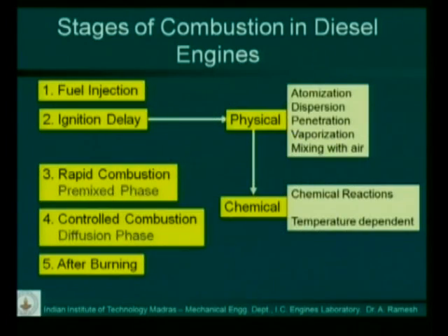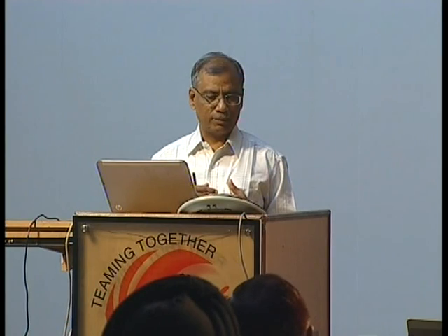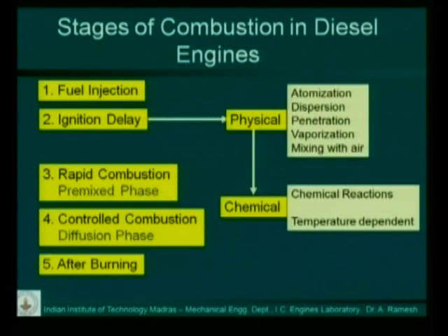Now, the stages of combustion in a diesel engine, I believe you already have been told about this, but I'll briefly go through this. So the diesel engine combustion starts with fuel injection. We know that we take air alone, we compress this air to a high compression ratio, and the temperature goes up to fairly high levels, and then we inject the fuel, and this fuel is injected as a fine spray, and the moment it is injected, it doesn't burn. So it stays in the combustion chamber for some time, and this period where it stays in the combustion chamber